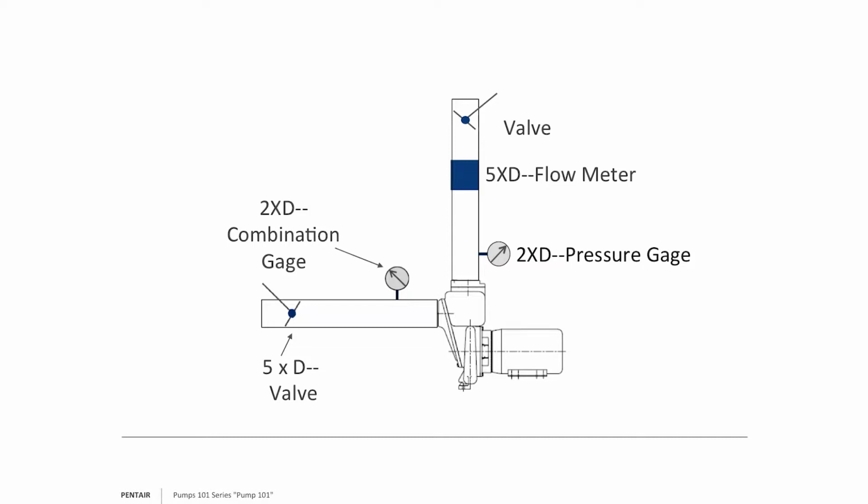All right, now knowing that's how we set this up, our engineers then would have the flow so it shows 0 foot of lift. Basically, the water is free flowing into it. So they set up their suction side, they then get the discharge flowing, and then they'll close off that valve all the way to get the maximum pressure the pump can build, and they'll record it. Then they'll open up the discharge valve to get, say, 5 gallons per minute of flow, and adjust the valve on the suction to make sure it's at 0 feet of lift again, and they'll get the pressure reading for that. And then they'll go to 10 gallons per minute, 15 and 20, 25, until the pump runs out of available water production due to the size of the impeller.